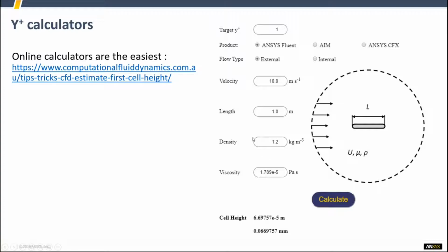And what can we tell about that? We can tell that we're looking at something that's very Reynolds number specific. Remember, Reynolds number is velocity times length times density over the viscosity of the fluid. Based on our Reynolds number, we know what the height of the Y plus is, generally speaking. Obviously, it changes, but we can get a good first guess.